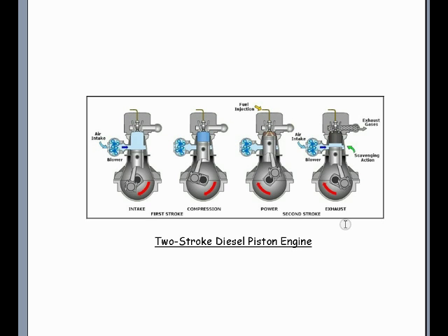Lastly, we have the 2-stroke diesel piston engine, which, just like the 2-stroke gasoline piston engine, the downstroke is the power, air intake only, not air and fuel intake, and exhaust events happening on the downstroke. And the upstroke is heat of air compression and fuel injection.